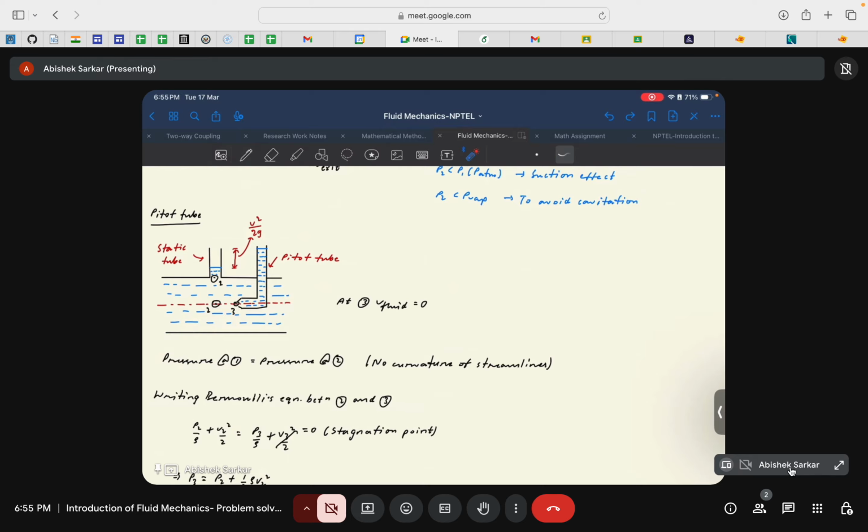The interesting thing is the pitot static tube, which is a device of this form, as shown here, which is an L-shaped tube with a very small opening at its inlet. Okay, so this is the tube's inlet. So what happens is that whenever the fluid strikes this location, when it is inserted in a channel or in a pipe, the velocity of the fluid at the point at which it strikes this small opening becomes essentially 0.